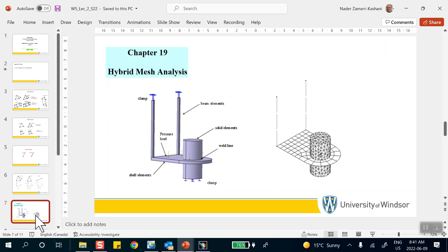Now you have two possibilities. Make this entire thing in a single part. That's option number one, and I'll show you how to do that. Or make several parts. For example, that sheet you can make as a separate part, that cylinder as a separate part, those lines either both at the same time in one part, or two parts. The point is that you can make this as 4 parts, for example, bring it into an assembly, and start from that point on.